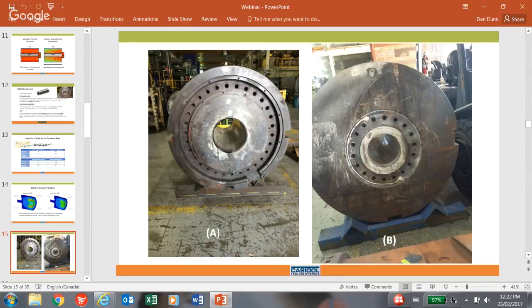The element location relative to the bore and thermocouples increases the opportunity of cracking as the heat transfers from this outward ring of elements to the bore, and then from the bore back to this outward ring. This thermal movement contributes to the cracking of container mantles.